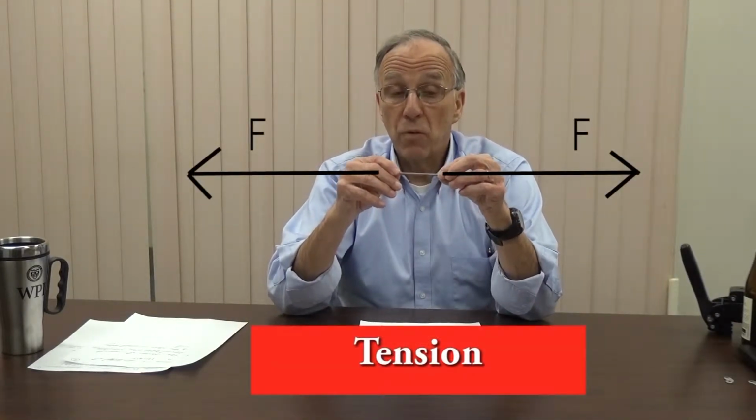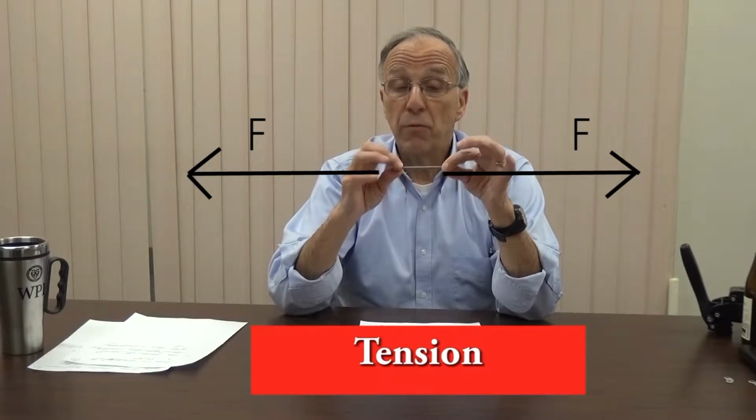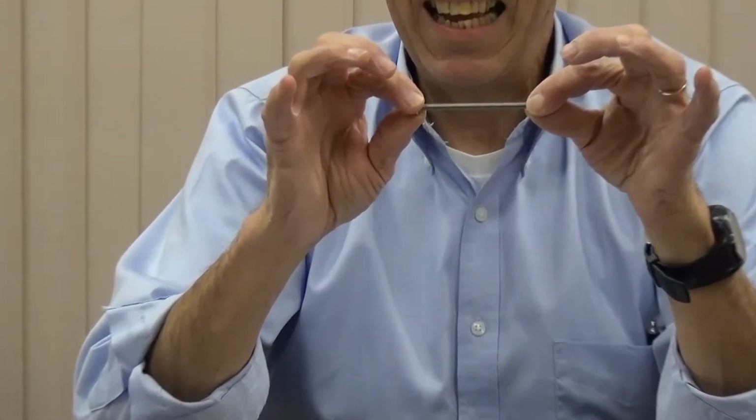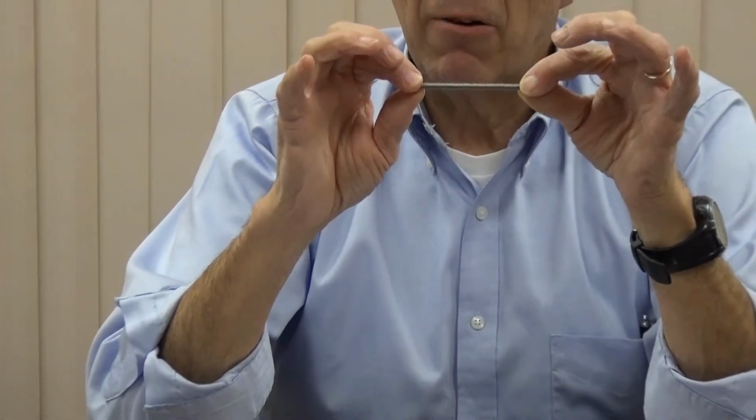Similarly, if I have a bolt here and I pull on each end, the stresses are based upon forces which pull on the bolt and therefore place the member in tension. If I get far enough away from the point of application of the forces, I can assume that the force is evenly distributed over the cross-section of the area, whether it's in tension or in compression.